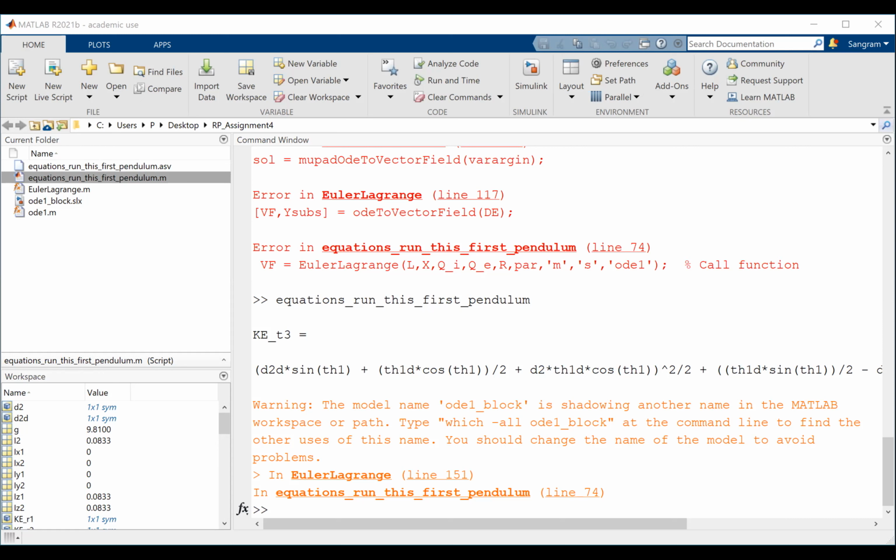Okay. And then if you move up, there are parameters. And right now we are not having any parameters. If you actually parameterize the robot arm, so for an example, if the end effector mass is changing. So for an example, that robot arm goes to point A, picks up something, goes to point B, which means the robot arm mass is changing. That will be defined as this parameter, and then you will change that parameter in your code. But we will look at that not now, later. But right now, this is how the equation is set up.